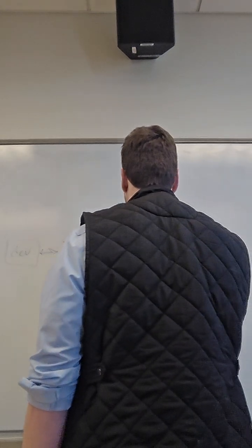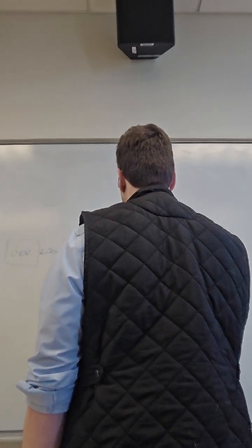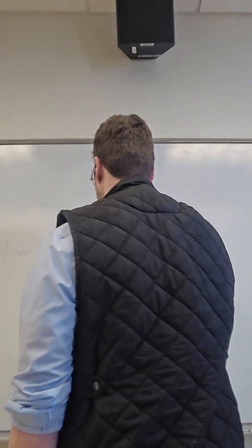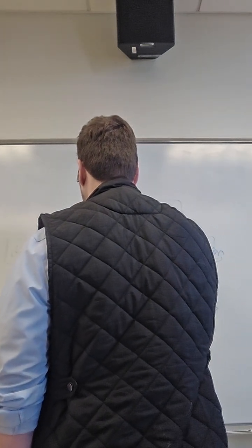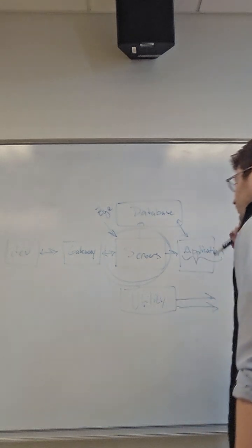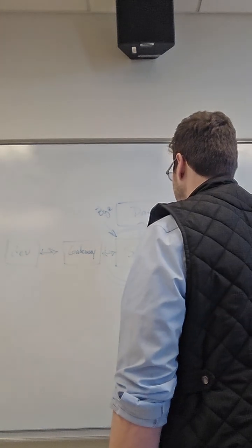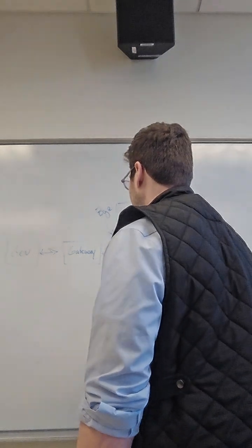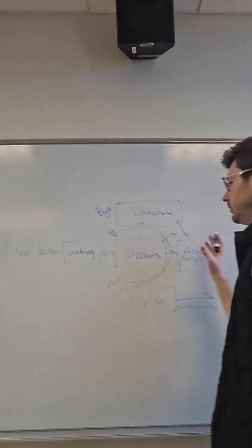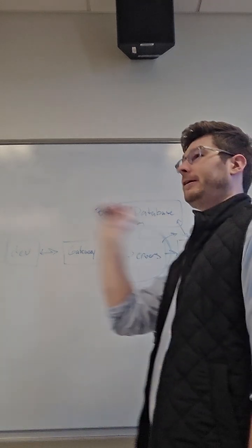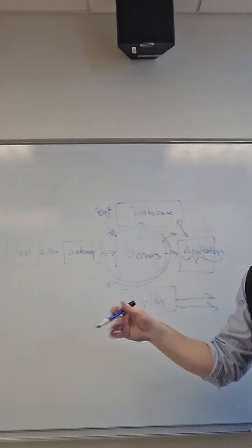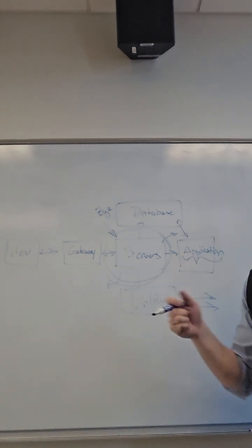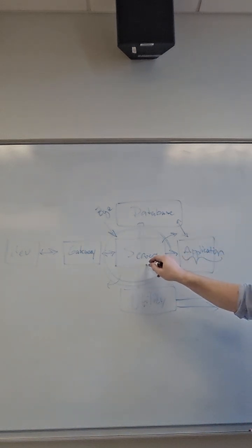So this is our third stage. Actually, it's just our application, our edge server. This is where we can do certain things with our information. We can trigger alerts. We can control end devices. So your server might go, if a device temperature is high, turn on a fan, and that might be a different device. So one device might be a temperature sensor, one device might be a fan, and the thing that links the behavior of the two is our application server, right?